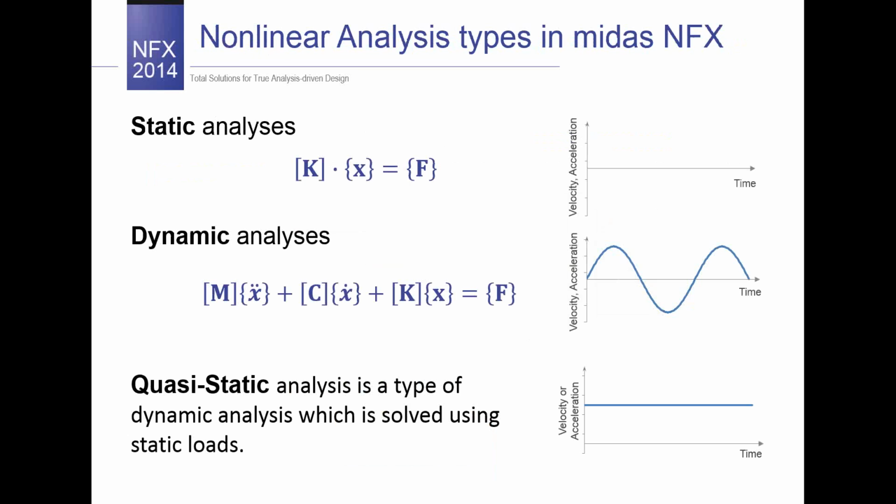On the next page, I would like to briefly introduce you the nonlinear analysis types in Midas NFX. So Midas NFX supports the nonlinear static analysis, nonlinear dynamic analysis, and analysis which is called quasi-static. And in a static analysis, let's say like a stress analysis, FEA is done using the simple, let's say linear equation, but in the nonlinear analysis, the stiffness matrix is nonlinear. That's why we are talking about this, that this is nonlinear analysis.